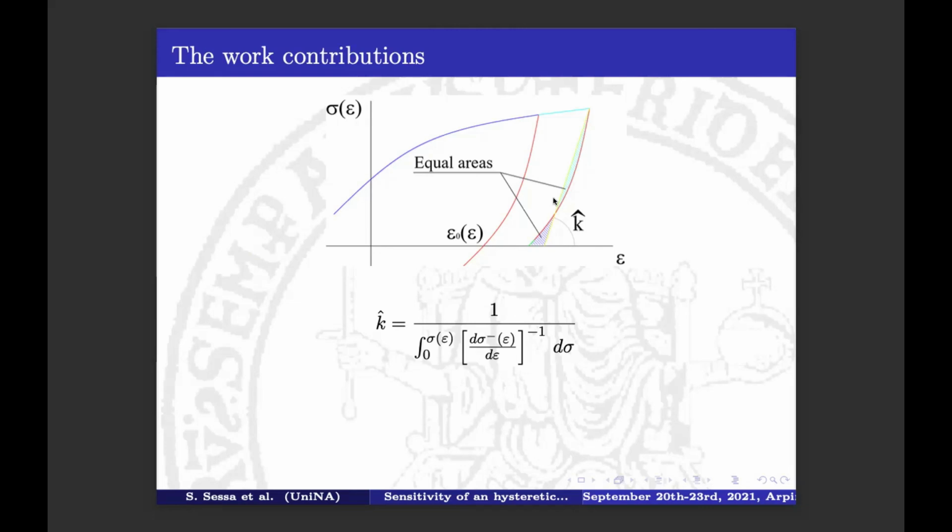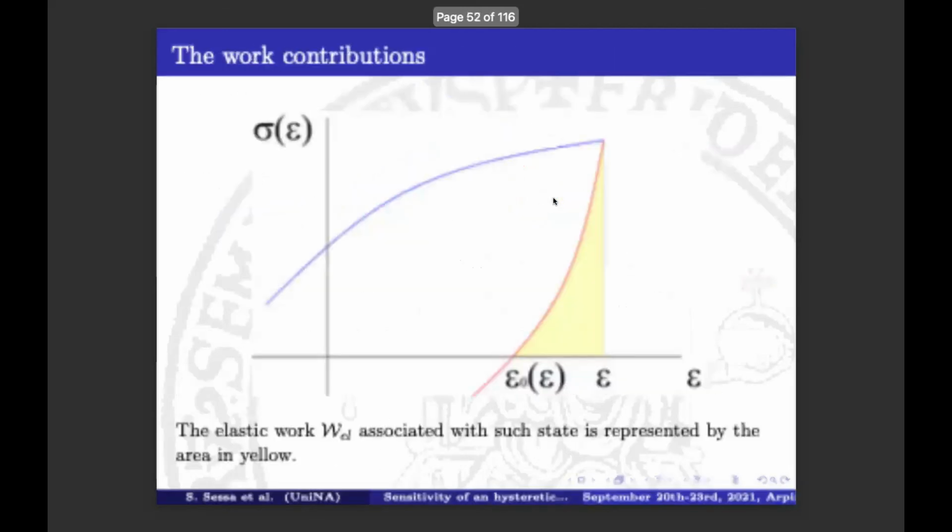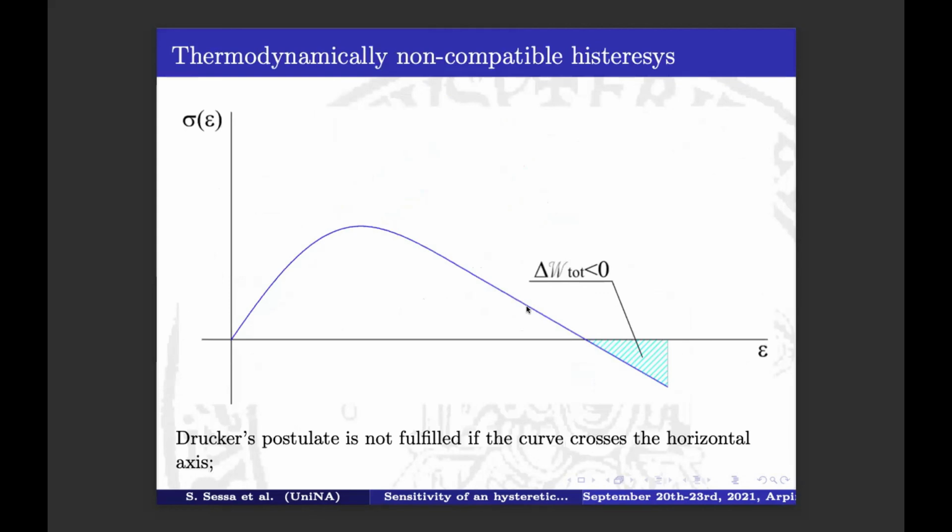So both the minimum and the maximum are a kind of asymptotic conditions. And in my experience, we were never capable of achieving non-compatibility for seismic cases. The more frequent case of non-compatibility was related to this behavior here. When we have softening, it happens that the curve reaches the axis and then we go out of the bound.